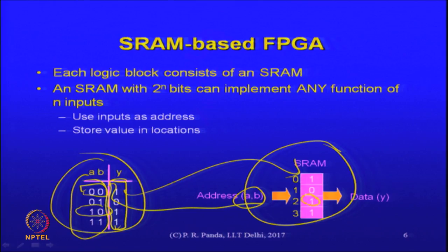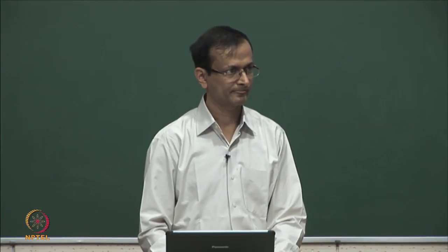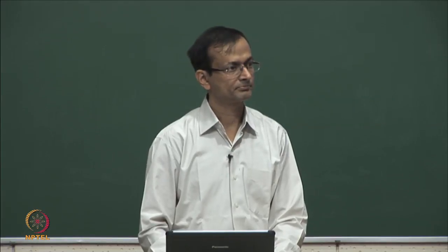But why don't we see a slightly more complex example? At the heart, the idea is this. The lookup table is called that because much of the implementation is through a lookup. There is a little bit of other logic also. There are some separate flip flops also. These are also memory elements, some D flip flops might be part of it. We are just storing the input at the start of the program, and no matter how the program proceeds, these values will be retained as they are.